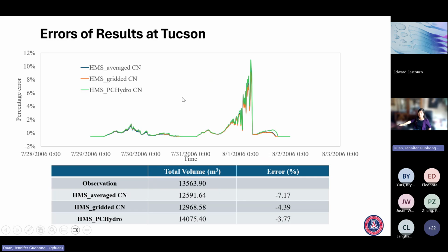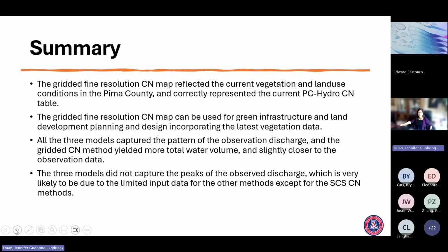So then this is the result at Congress Street, and the water volume prediction is relatively good, and then we miss a little bit because the total amount of water is very important in our region during that event. How much water you see in Congress Street, and this is showing you the predicted results. This is not that bad, but it is like 12% error. Okay, 12% error.